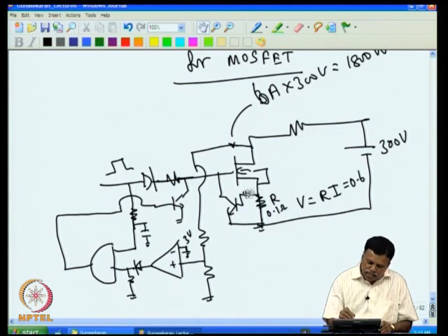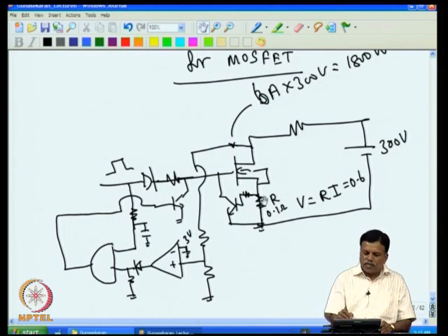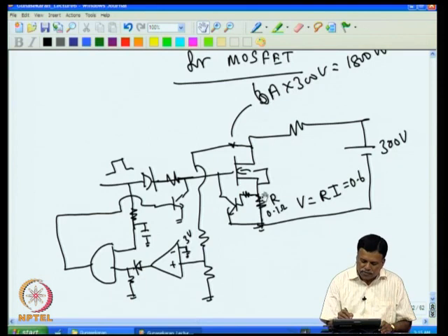this voltage will go high, and then this voltage will pull down to around 5 volt, because if it pulls to 0 completely, this voltage will disappear. So it will not normally pull down. This will be sitting around 5 volt, and this will be conducting that 6 ampere current I discussed earlier, because that depends upon the 0.1 ohm I have put. So 0.1 into 6 ampere will be 0.6 volt. So at 6 ampere current will be flowing, and that will make this voltage go high, and if this voltage is higher than 3 volt, that will come high.